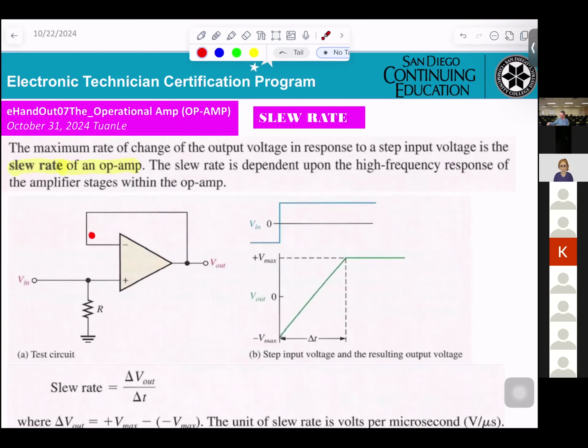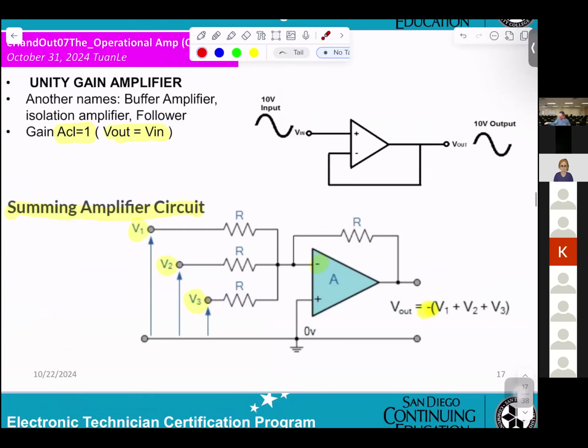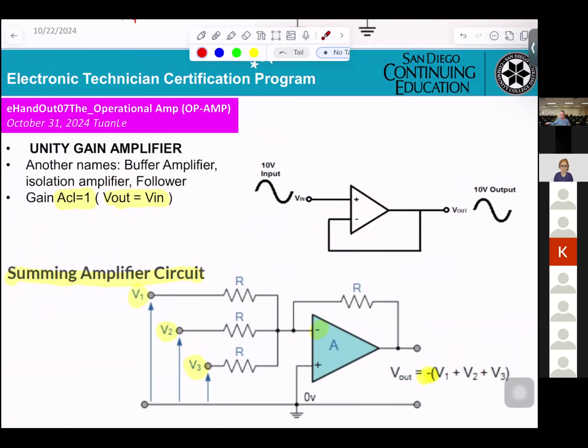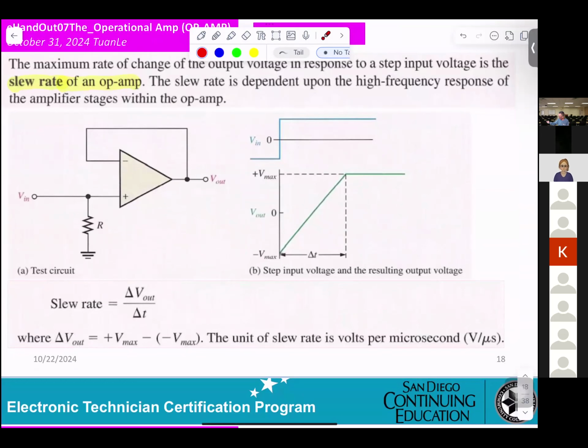You see, the output connects back directly to the input. So that is a unity gain. Input and output will be the same. That's what we just went through here. Now, see what happened. If you're looking at the input, this is the input here. However, the V out is not exactly the same. That's the V out here. You see that? They delay. They will be okay here, but at the beginning, they delay for delta t, take a little time, before they try to get exactly the input applied.